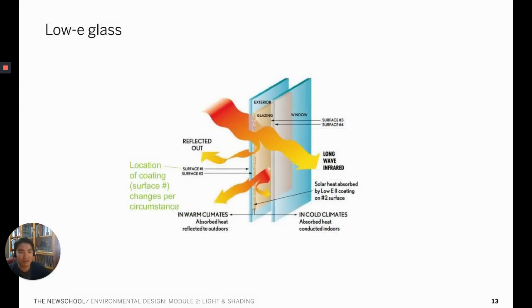When daylighting is desired and solar heating is not, having the visible component of solar radiation pass through while heat radiation is blocked would be very advantageous. Certain spectrally selective glazing systems can do that. For example, low-E glazing allows visible light to transmit while blocking a certain amount of infrared radiation.